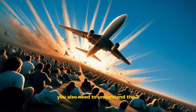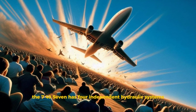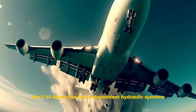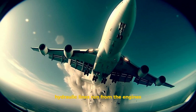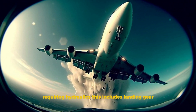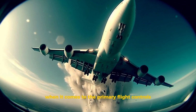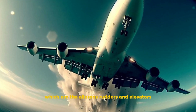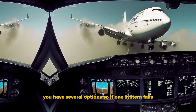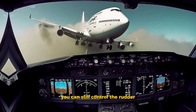You also need to understand the 747's hydraulic system. The 747 has 4 independent hydraulic systems, each powered by its engine. Hydraulic lines run from the engines and hydraulic pumps to each system requiring hydraulics. This includes landing gear, flight spoilers, and the primary flight controls. When it comes to the primary flight controls, which are the ailerons, rudders, and elevators, you have several options. So, if one system fails, you can still control the rudder.